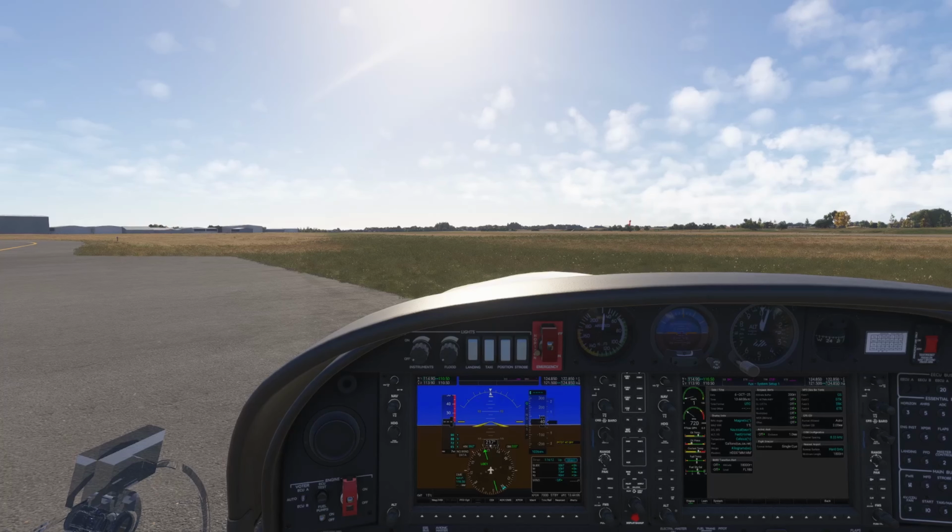At the end of the runway, we're going to turn right 10 degrees, and then at 300 feet, we're going to reduce the power to 90%, which is a requirement for the NG. And then we're going to climb at 80 knots. Once we're over the coast, we will resume own navigation. We'll set the bugs climbing up to 2,000 feet. And we'll set a heading bug.